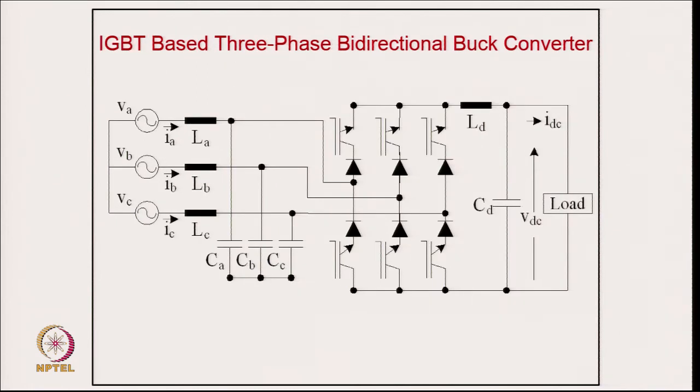And this is the circuit with the IGBT with series diode. The reason is that this is a current source converter and you have a pendulum current here, and it needs reverse voltage blocking capability across the switch. That is the reason: IGBT or MOSFET, the transistor family, does not have reverse voltage blocking capability, so for reverse voltage you connect a diode. One of the major drawbacks is that there are now losses of two devices, not one.